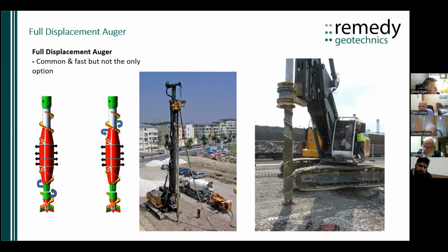Okay, now another question from Hazik Zahir. He's asking, since the soft soil at the top has more residual settlement than the rigid inclusions, I am assuming the soil settles. Doesn't this induce concentrated stresses in the upper region of rigid inclusions? Yes, it does, and I will come and show some.